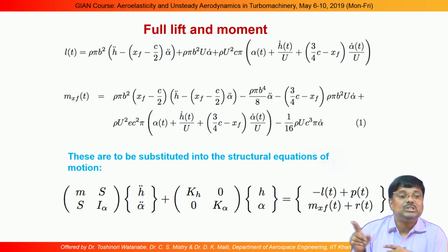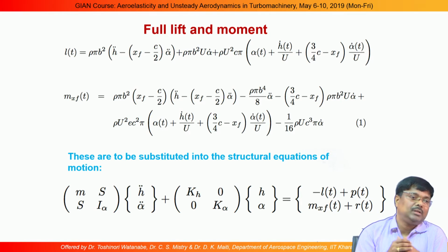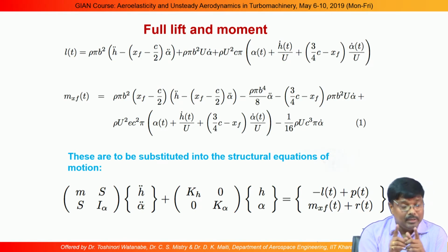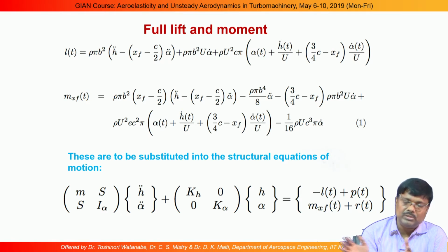The mode whose frequency goes to 0, at that point damping also will become 0. That is the divergence speed. When damping becomes 0 but frequency does not reach 0 and has non-zero values, that we call the flutter point. Usually flutter happens before divergence, that is why flutter is more important than divergence. Divergence may not be feasible in the range of velocity the aircraft can fly.